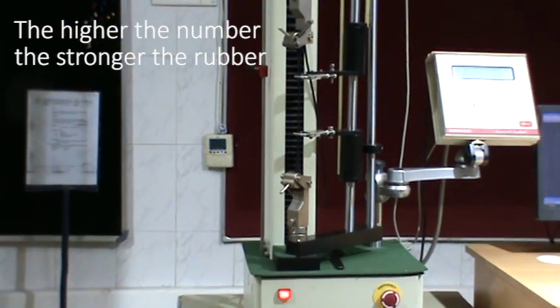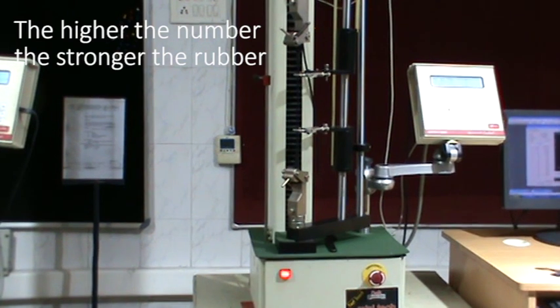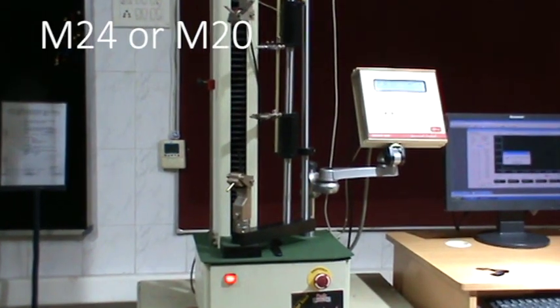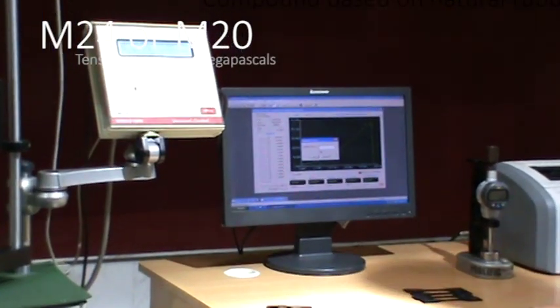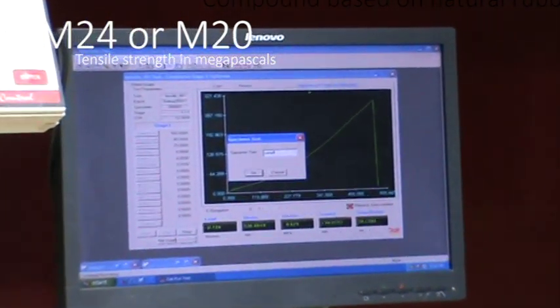The tensile strength of the rubber is closely related to the rubber's resistance to cutting and gouging by sharp objects. Belting with rubber covers of high tensile strength are often quoted as being M24 or M20, whereby M signifies it is a compound based on natural rubber, and 24 or 20 denotes the tensile strength of the rubber in megapascals.